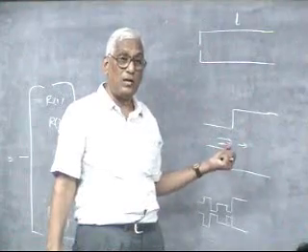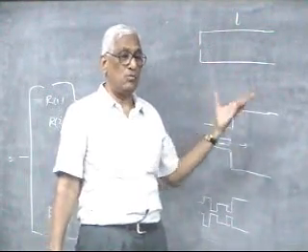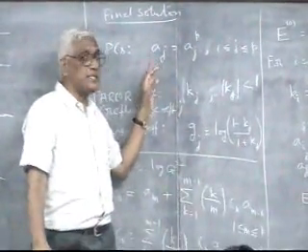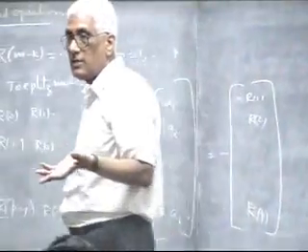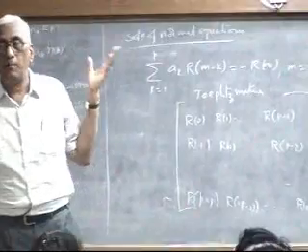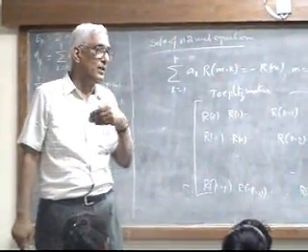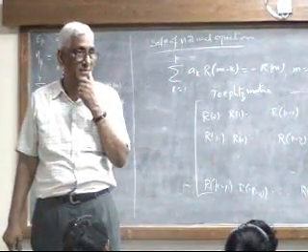But of course, our interest is, if you want to look at it as speech, the more important thing is that people hammered out these studies so much, because from the communication angle, after all, LPCs, if you start coding, you are in disaster. Because the whole problem is LPCs are nothing but the coefficients of the polynomial, that A(z) polynomial, and you notice that every coefficient virtually needs to be represented with infinite precision.